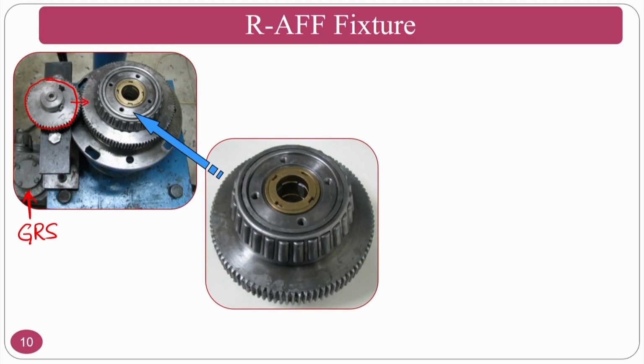there will always be a chance of leakage. So, in order to prevent the leakage, you should go for things like a multiple gear system and O-rings, as well as some gaskets and other things we have used, which are not shown here. So, O-rings are used so that it can become leak proof. Then in some places we have used gaskets so that it will completely become a leak proof system.